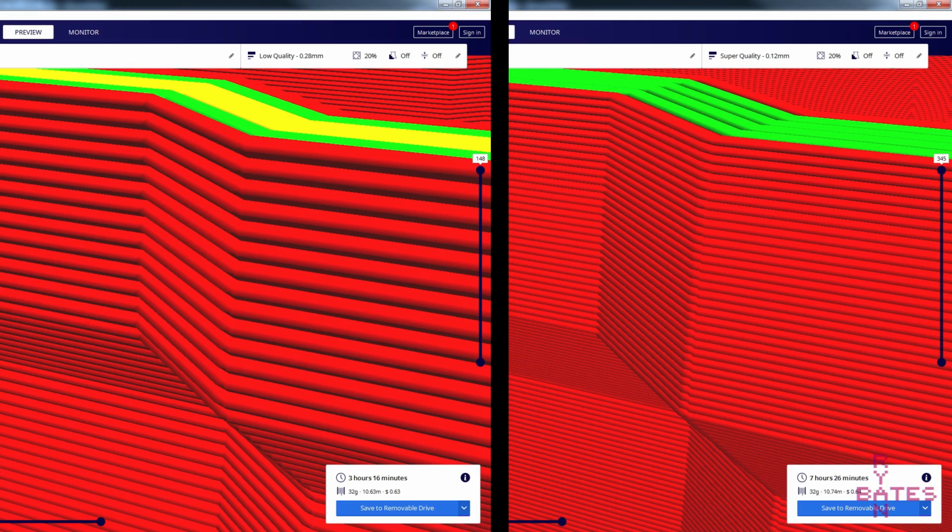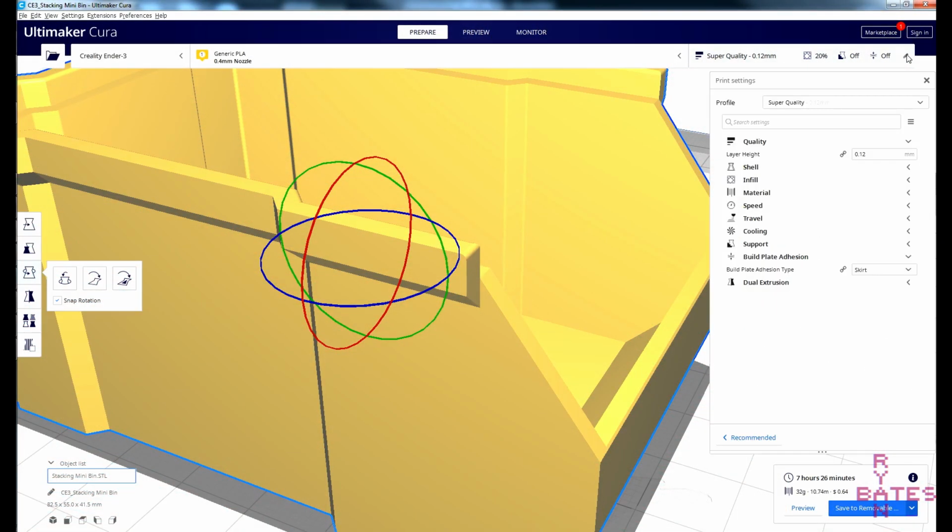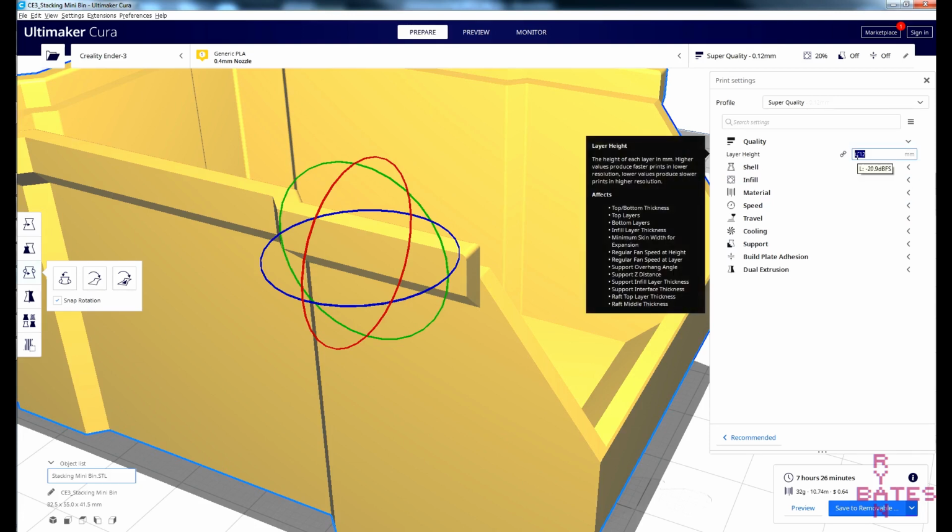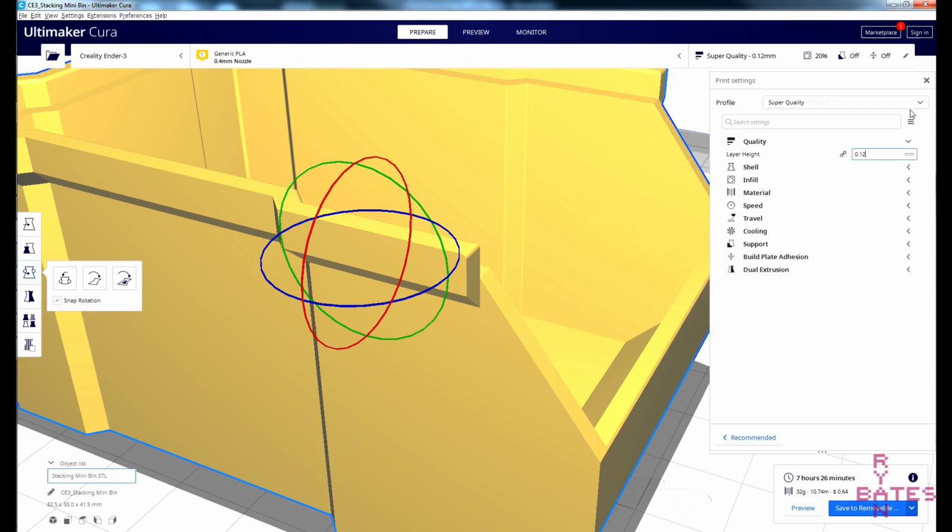The actual print speed, or in literal terms, the speed the printer is laying down filament, is typically held constant between changing layer heights or print quality settings. Changing the print speed to a value faster than the recommended setting has a cascading effect on almost every variable related to a successful print. Changing the print speed is not recommended for beginners. Adjust your layer height or slice thickness if you need a faster print. The slicer preview or layer mode is a good way to illustrate this point between print qualities.